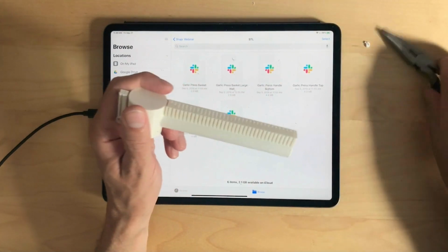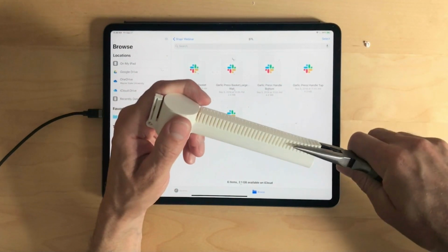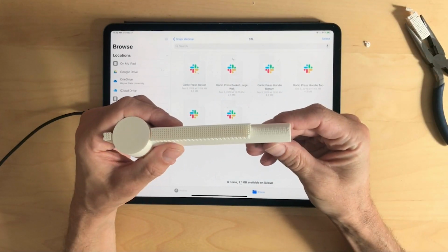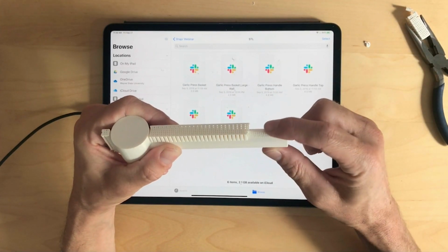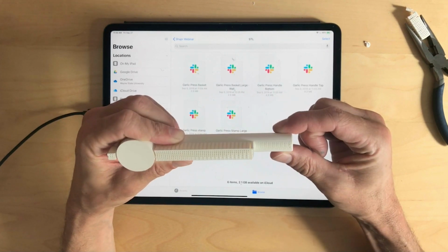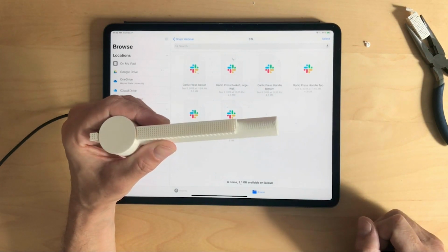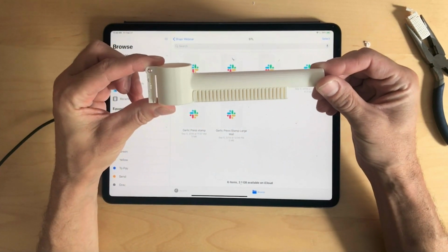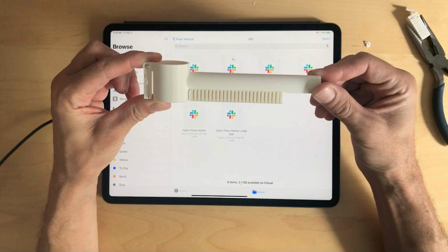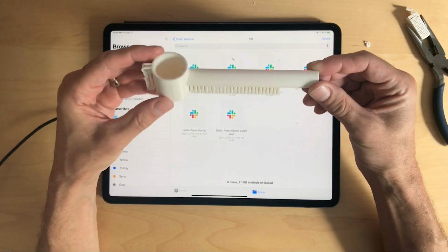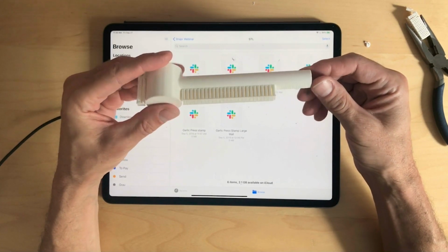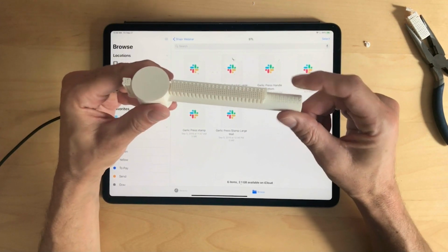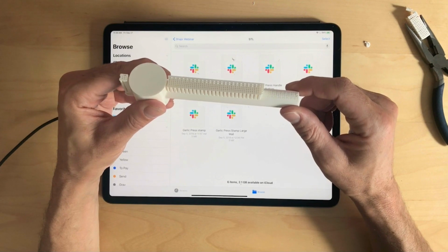If we go to this model maybe here, there we see this even better. This is now with finer supports, and there you can see that structure. Now this is not visually desirable, so positioning your object in the printing queue also can have an impact on the quality. So where you don't want to see these print leftovers, try to have the support.